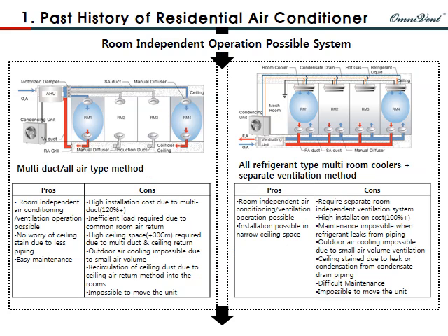Now, in order to realize room-independent operation, here's the multi-duct all-air type and all-refrigerant multi-room cooler with a separate ventilation system. First, the left image shows room-independent air conditioning and ventilation operation, which is very easy to maintain and is worry-free of ceiling stains due to its minimal piping. However, on your right, its disadvantages are its high installation costs due to running multiple ducts to each room,